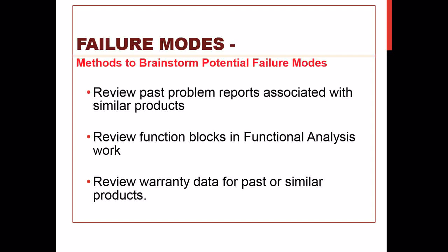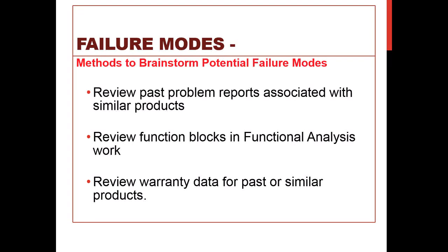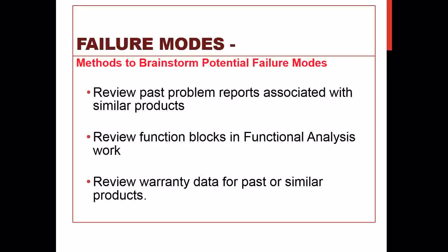Also, we want to understand that the failure mode can also cause potential failure modes in higher level assemblies, and we can track this through the function tree. So we want to understand failure modes. The other thing you also want to understand is the effect, the impact of the item's functionality on the performance as perceived by the customer, or more specifically, the user of the product or process.